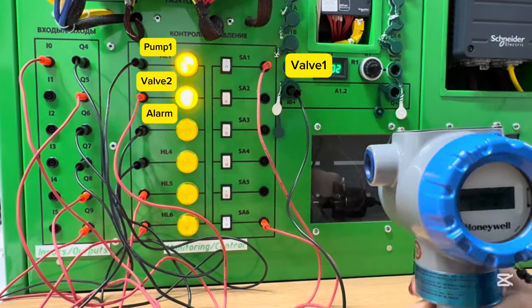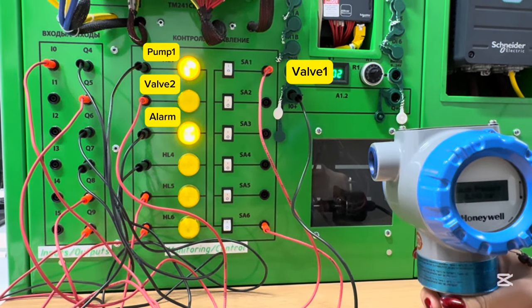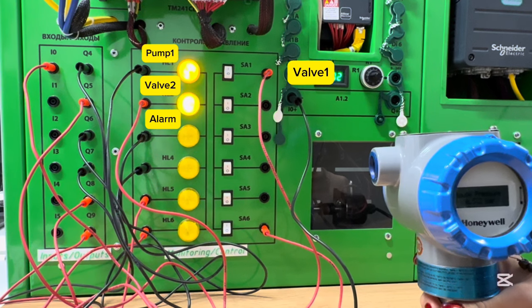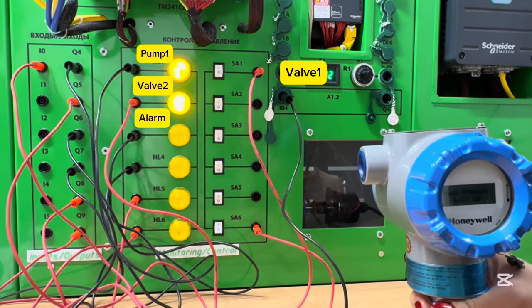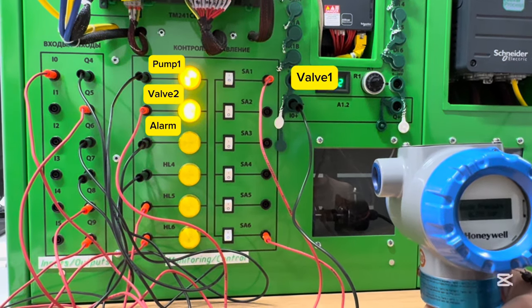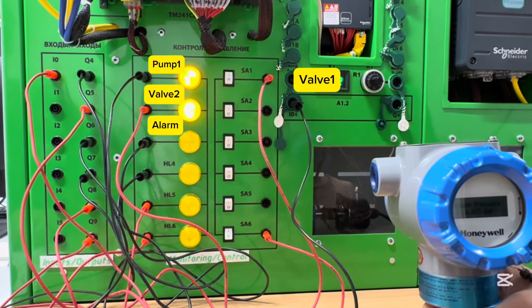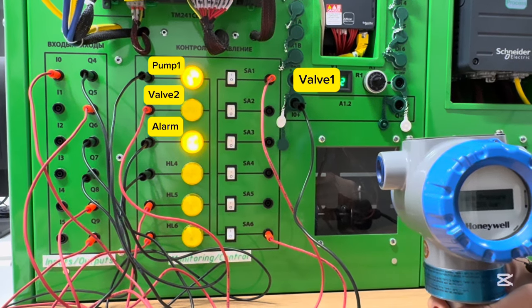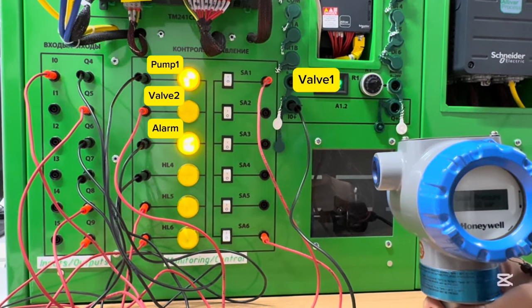As you can see, we then activate valve 1, which sends an electrical signal to pump 1. If the pump runs properly and the pressure returns to the normal range, valve 2 opens, allowing the sodium hypochlorite solution to move to the next stage of the process. As additional information, we scale the pressure signal so that 0.1 bar from the transmitter corresponds to 1 bar in the system, allowing for easier interpretation and control.